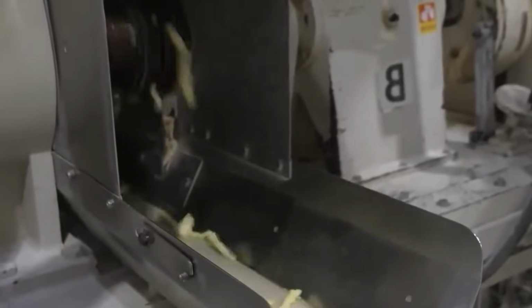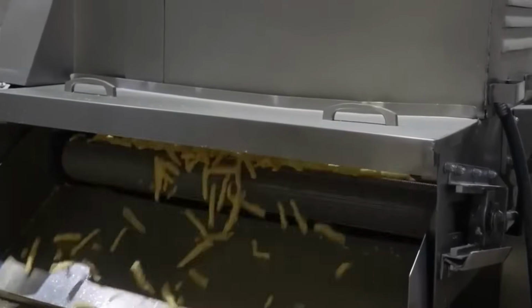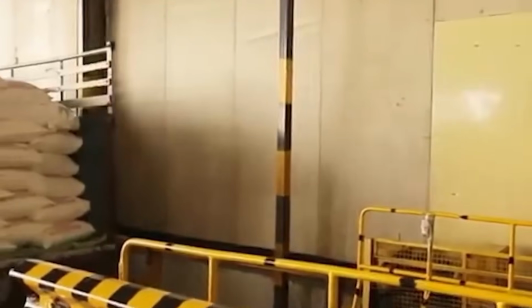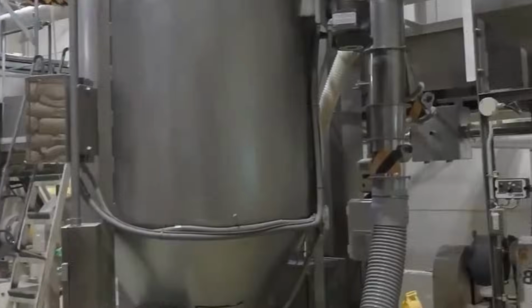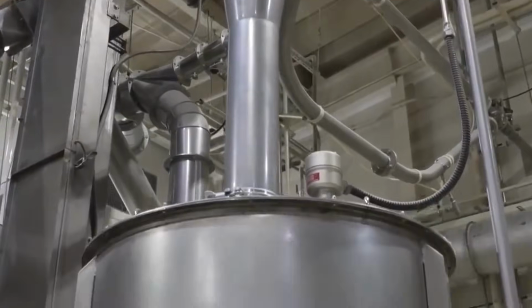Cheetos are produced using a high-output, continuous extrusion system designed for the transformation of dry cornmeal into expanded puffed snacks through controlled heat, pressure, moisture, and mechanical shear. The raw material input begins with degermed cornmeal, which is stored in silos, connected directly to the process line through a network of pneumatic conveyors.